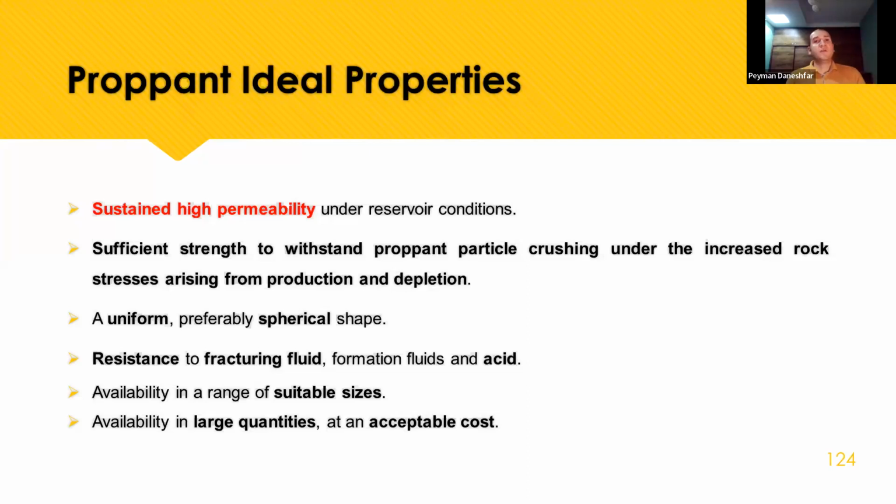So our ideal proppant properties are sustained high permeability, sufficient strength to withstand proppant particle crushing under the increased rock stress, a uniform, preferably spherical shape, spherical without any edges, resistance to fracturing fluid, formation fluid, and acid, availability in a range of suitable sizes, availability in large quantities, and at an acceptable cost.